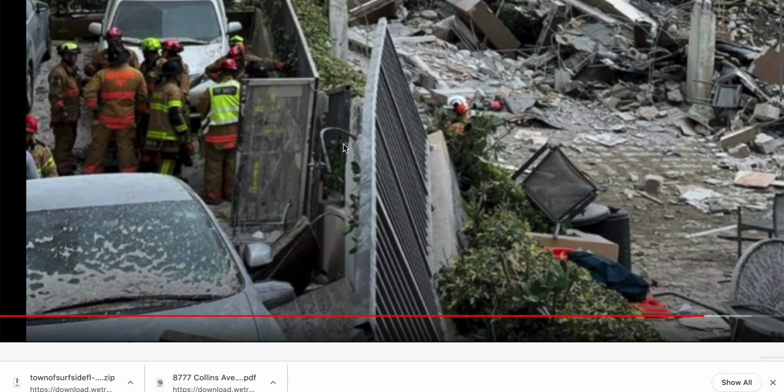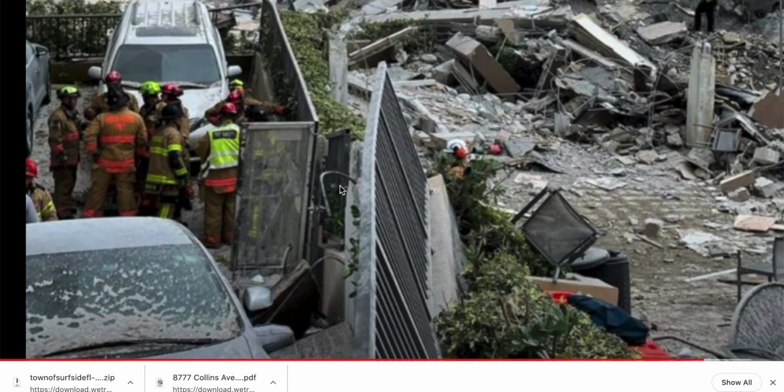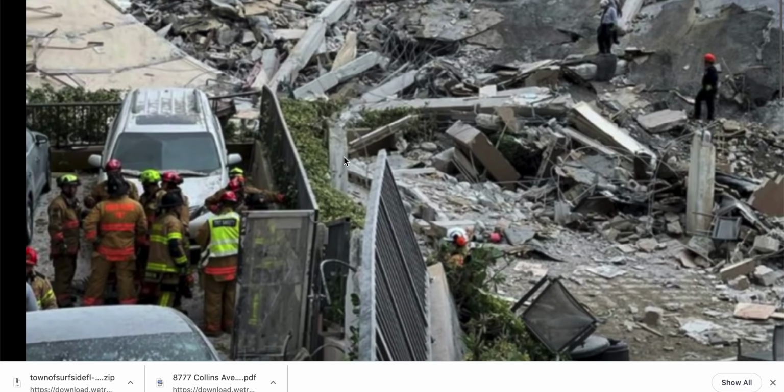All right, and it looks like there's the rebar connecting maybe the deck, or it could be part of this column. I think it's the deck, because on these heads, so far, we've only found four pieces of steel coming out max. 2 and 2 this direction, 2 that direction. I don't see any other direction bent over, well, because I just don't see it from this video.